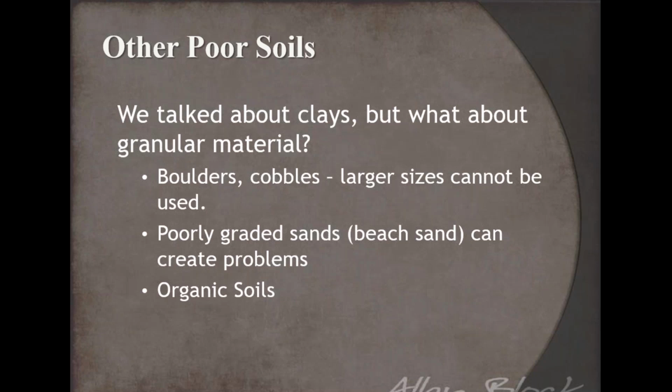And then I've already mentioned a little bit about those organic soils. Obviously, anything with organics in it could decompose over the lifetime. And so anytime they decompose, they're going to settle, which is why anytime there's excavation activities, we're always looking for those organic soils and removing those and replacing as we go.